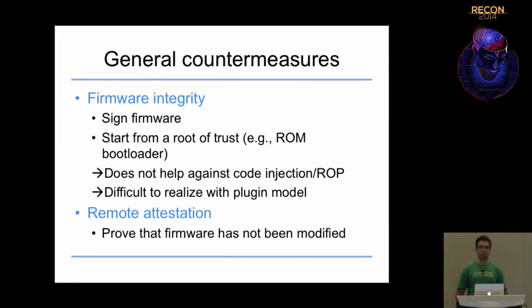And it's also very difficult to realize firmware integrity with the plug-in model that is inside this hard drive. If other people are allowed to load code inside your execution system, then you would need to check these signatures too, and then it gets more difficult because then you need to have a certificate authority, and this is most probably above the head for just a hard drive. A solution would also be to have remote attestation to prove to the host that the firmware has not been tampered with, but I think this is still an area of research.